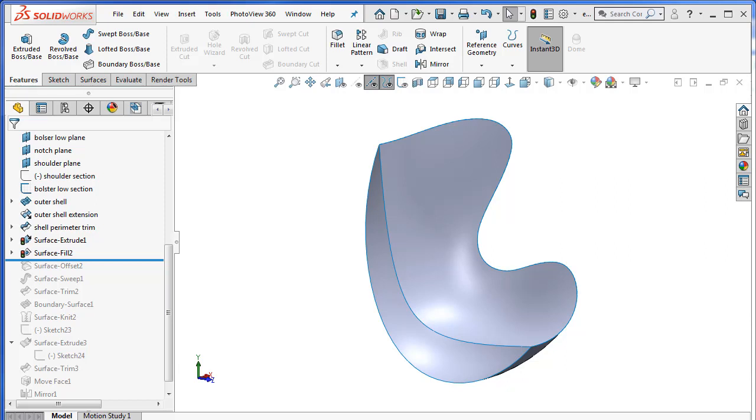I've noticed that there's certain problems that people who are building an egg chair or a womb chair run into, and that's because there's some similarities in the way those two chairs are constructed. Both chairs involve making some sort of a primary surface. In this case, I'm using the egg chair as an example, and we have an outer shell surface and an inner seating surface. And the idea is to offset the seating surface and later on build a transitional surface back to this edge to give the impression of a seating surface that has some cushioning in it. And the same is done with the back shell as well.